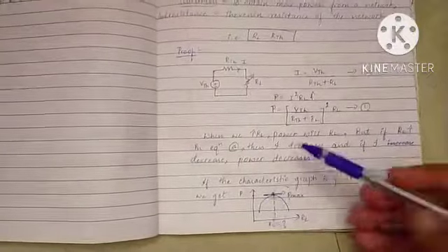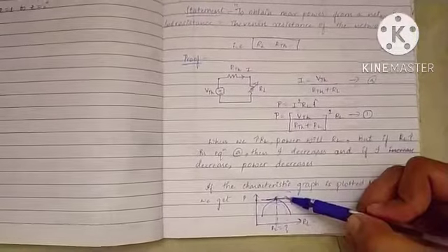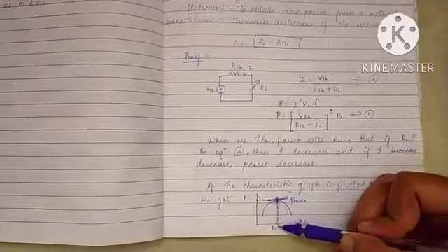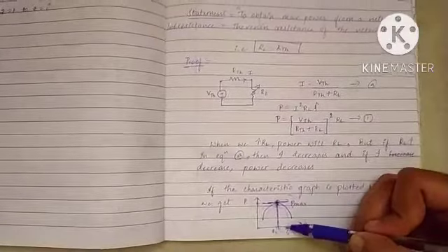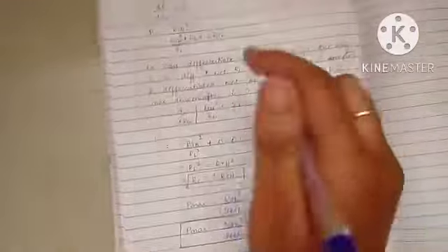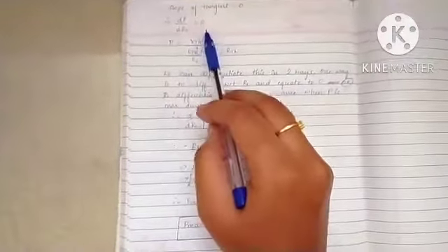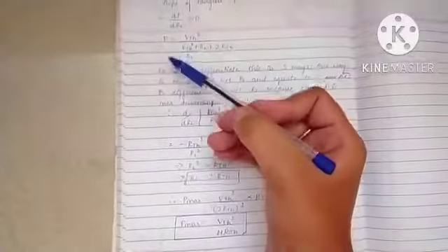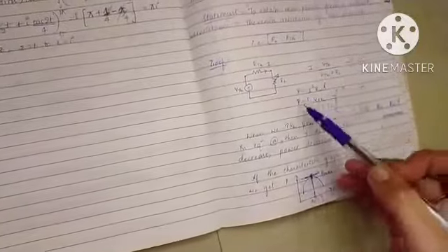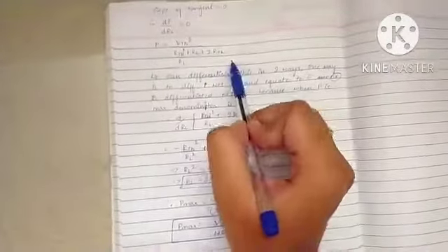Next, here is the maximum power obtained. So when we consider a slope here, the corresponding RL value will give us maximum power. Next, we can find that the slope of a tangent, that is dP by dRL, will be equal to 0. Next, in this power equation, we are going to expand this equation. When we expand the equation by squaring this term, we get this term.